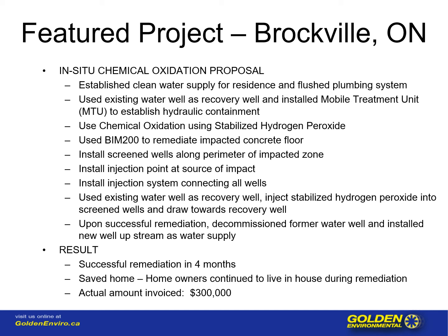Then we installed screen wells along the perimeter of the impacted zone. We installed injection points at the source of the impact and then installed an injection system connecting all of the wells together. We used the existing water well as our recovery well and injected the stabilized hydrogen peroxide into the screened wells, which was drawn towards the recovery well.